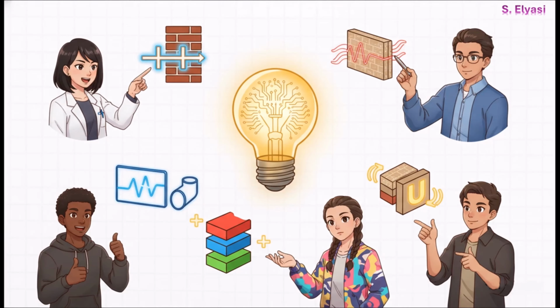So, what's the big takeaway from all this? The most crucial thing is that you can model really complex systems as just a simple circuit. Walls, pipes, insulation layers, they're all just resistors. You figure out the resistance for each piece, conduction and convection, add them up in series, and you can predict the total heat flow. It's an incredibly powerful tool.